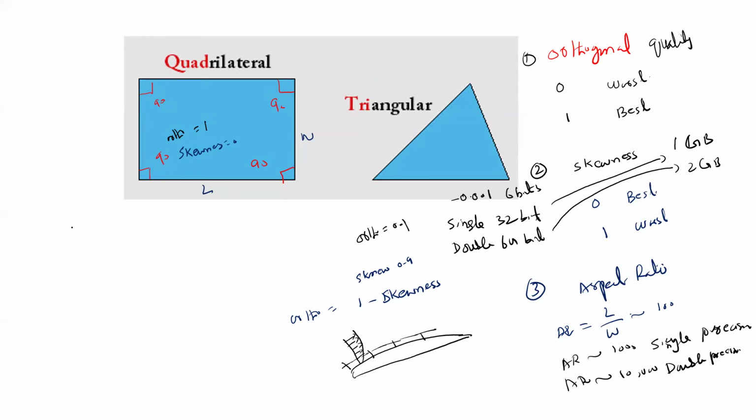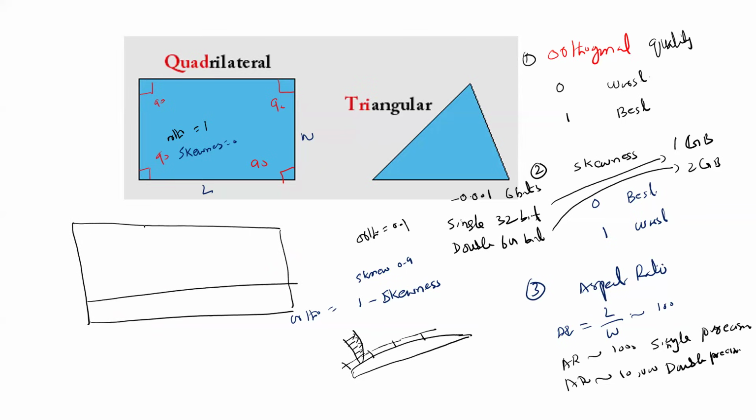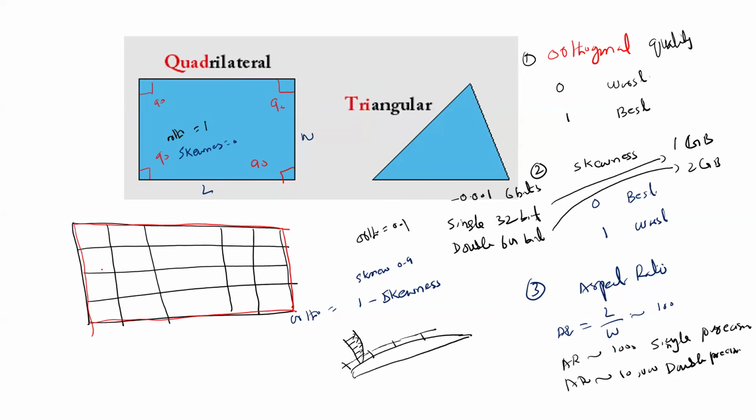See, when we have a mesh like this, we have boundary conditions on the boundaries. These boundary values are fixed, so we provide these conditions ourselves. Then from these boundaries inward, we solve the case for the results on these cells.